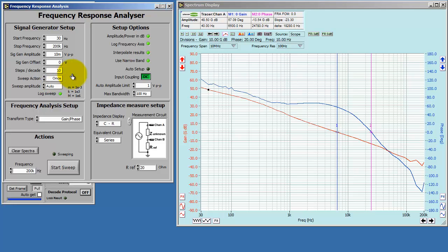Mostly we use auto because it adaptively finds the correct output amplitude to use to compensate for the gain of the amplifier that's inside the power supply. We can specify a log sweep, and we can use the standard MK suffixes in our units, as in 10 millivolts. This value is a peak-to-peak voltage. The RMS is approximately 2√2 smaller than that.